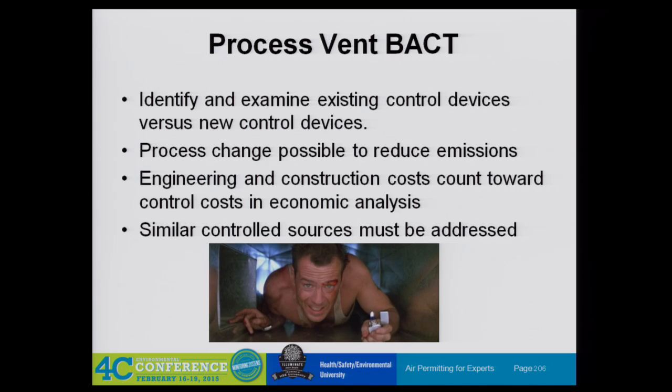Everything from concentration, the type of pollutant, the type of control compatible with the type of pollutant. Here, VOC isn't necessarily just VOC. Some things work great for benzene, but don't work for propane at all. Some things work great for hydrocarbons, but you put a ketone on there, it catches fire. So you have to look at the speciation sometimes one more level down than just the pollutant level, and make that argument in your BACT as well.